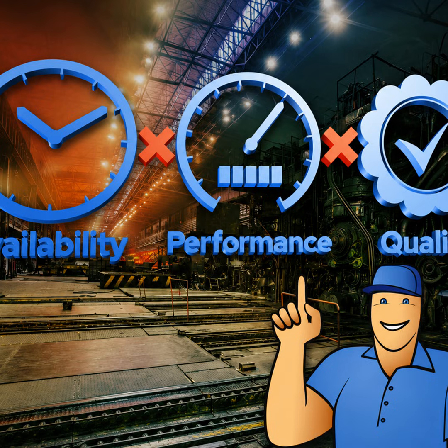Find out what's different on your best days and see if it can be replicated all the time. You can also look for ways to run faster without sacrificing quality. Test new line speeds, for example, and document the results. Often, a manufacturing process will run at one speed because it was necessary back in the day. But things have changed, and it's time to question long-held assumptions.